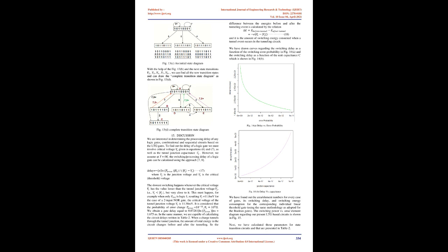This shifted vector is automatically ORed with the initial collision vector. Depending upon the value of the transition, we apply the clock pulses and get the required state transition from the output of the OR gates. We can take 2 right shift as there is 1 out transition equals 2. So after setting equals 1, 2 clock pulses are applied to get the new transition state 2 from the OR gates. We can repeat the process for the transitions 3, 4, 7, and 9 plus.